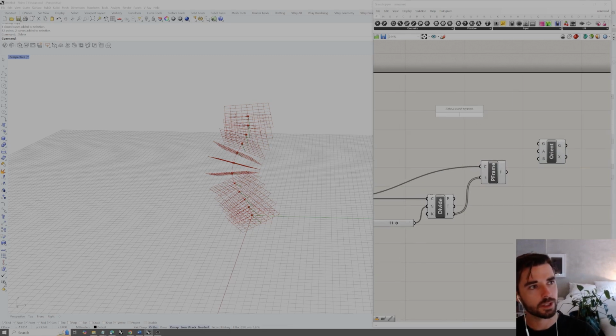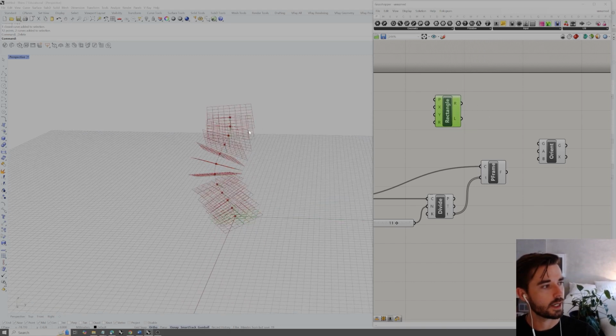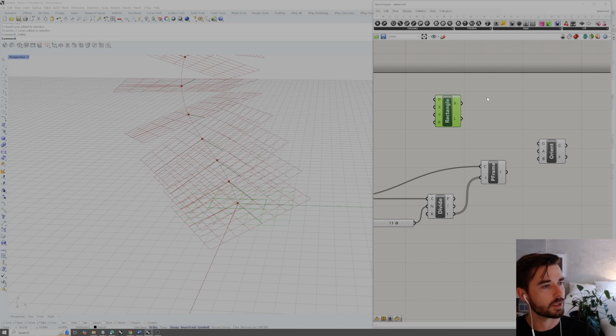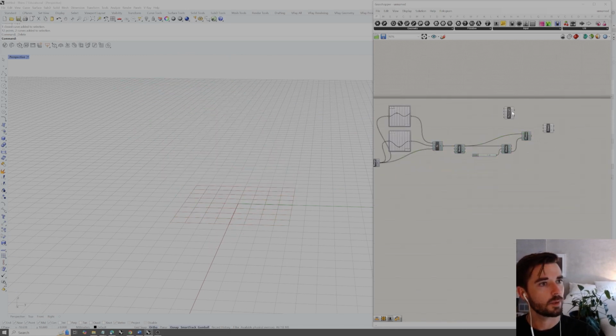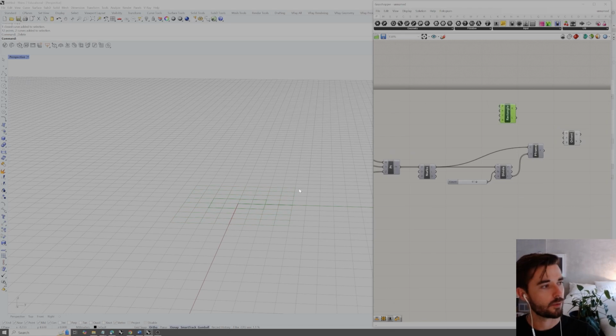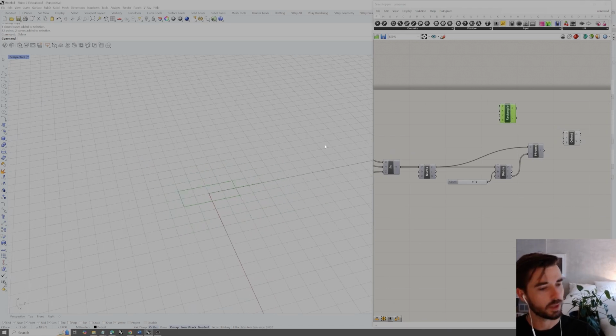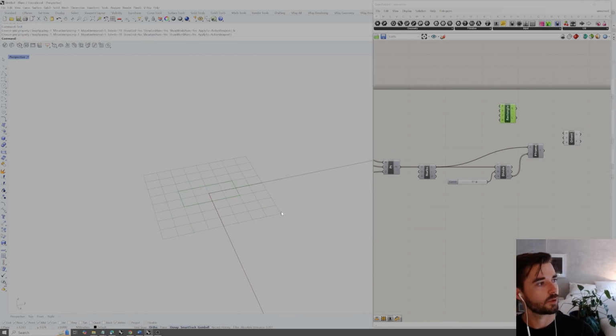So our cross section, we can just use a rectangle for now, and we're going to keep this parametric and make this rectangle inside of Grasshopper. Right now, it's probably drawing a very small rectangle. If we hide all of these previous components, we can take a look at that rectangle. The rectangle is previewing also a plane, and we have this grid showing, so let's just hide that grid, and now we can see that rectangle showing up right there.